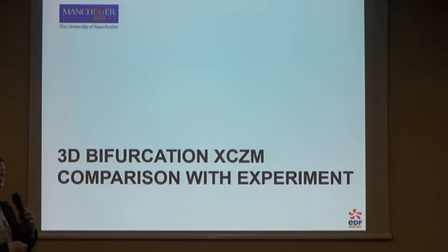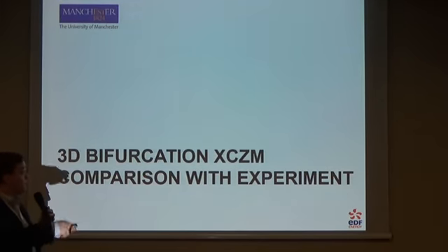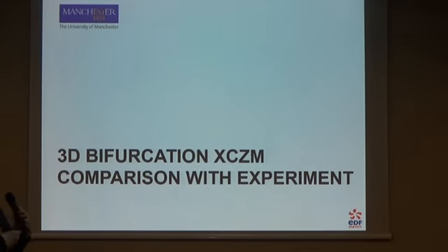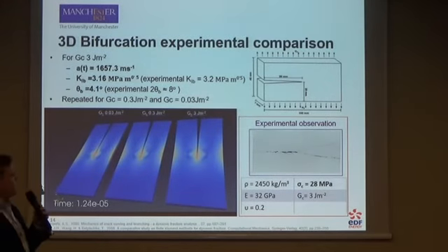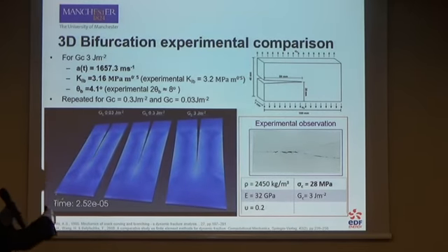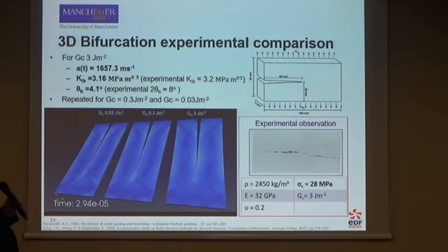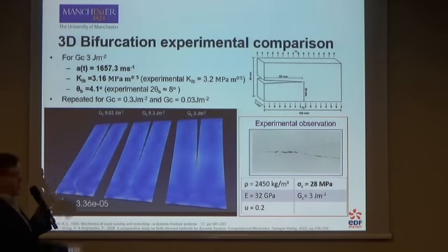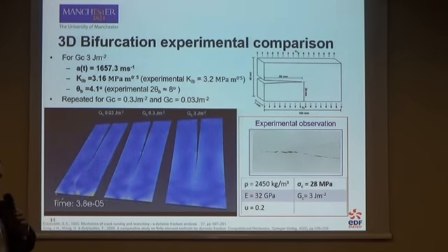So this being good news, putting it into 3D, looking at possibly bifurcation angles due to macro strain waves, and just doing a quick parametric study to show you the effects of initiation energy and what happens as the crack propagates. So under 3D, same experiment again, without any crack branching criteria, just a bifurcation angle from Rankine.